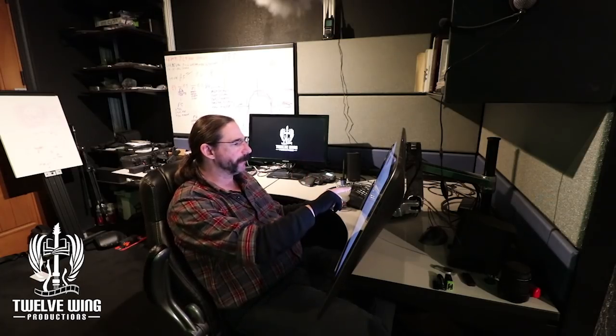For those that don't know a lot about the Tesla Powerwall batteries, there is a default safety circuit within the Tesla inverters that, when you're charging off of the grid, limits the charge rate of each Powerwall to 1.7 kilowatts. And obviously we have 6 batteries, so the overall charge is 10.2 kilowatts. So that's where that number comes from.